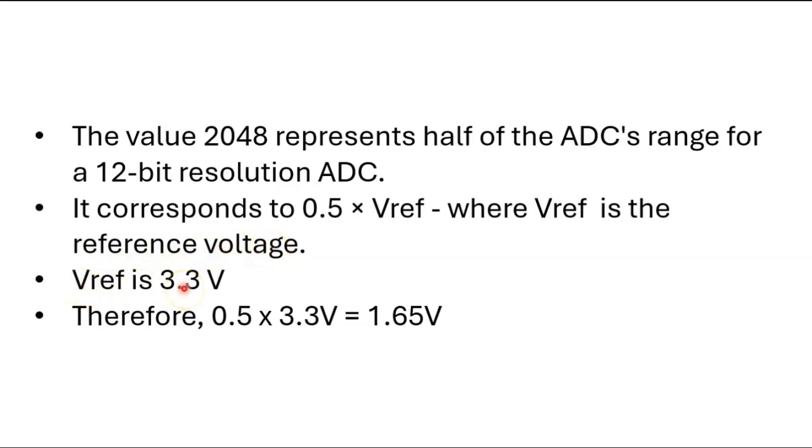Vref in our case is 3.3 volts, from the TM4C123G LaunchPad board. If you multiply 0.5 by 3.3 volts, we get 1.65 volts. Keep in mind this figure, 1.65 volts, which is equivalent to the 2048 value that we have chosen in our program.